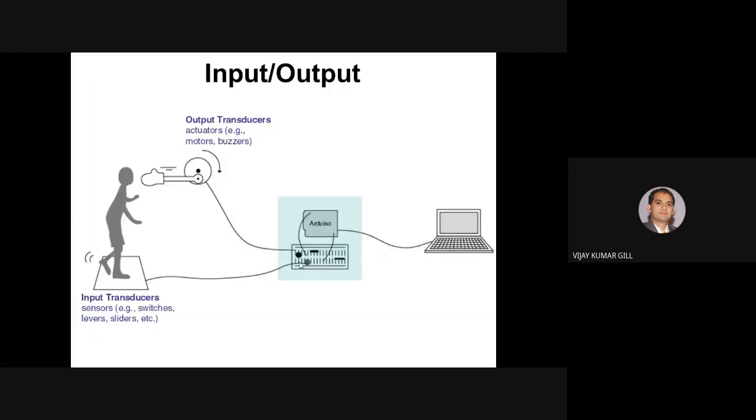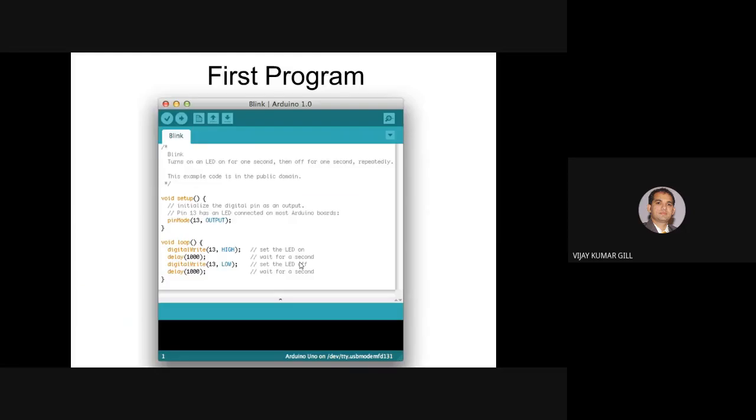In this project, I'm using an Arduino as our computer board, an output transducer, which is our micro servo motor, and an input transducer. Here, the input transducer is our Bluetooth, which is getting serial commands for our Arduino. So you can say for input, I'm using my Android phone. Inside my Android phone, I'm using sliders with the help of my thumb. Using the sliders, those values are converted to digital values that are passed to Bluetooth, and Bluetooth passes that information to my Arduino, and according to those instructions my motor changes. So this is my first program.